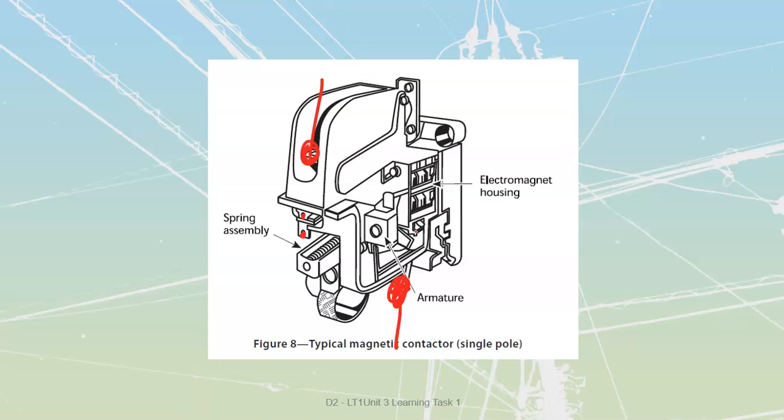And a magnetic blowout coil is this really cool thing we would see happening inside of here. This is going to be shielded because this is going to be something called an arc chute inside of here. And the arc chute is literally going to be composed of small fins inside of there. I'm just going to draw them for a second, that are going to be getting larger as we pull them further out.